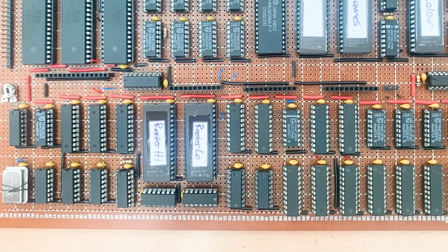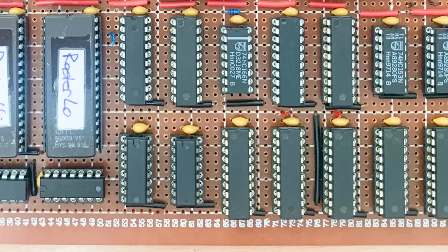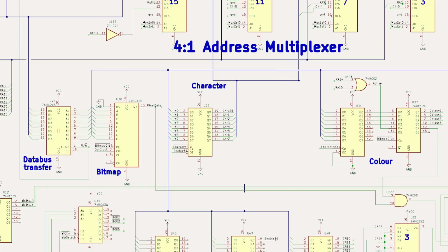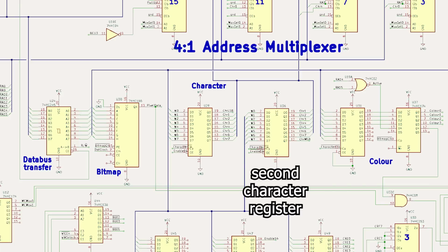By this stage of the build, I'd started to get a bit locked in, but I did have a spare 74HC574 wired onto the W bus. So I'll just latch the character into 2 registers and have the outputs offset by 1 bit position. This means I can just use the output enable to select the one I want.